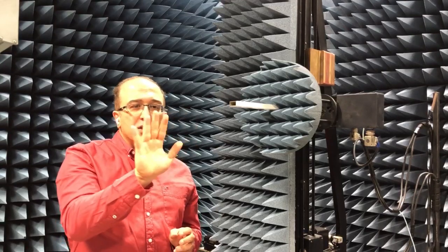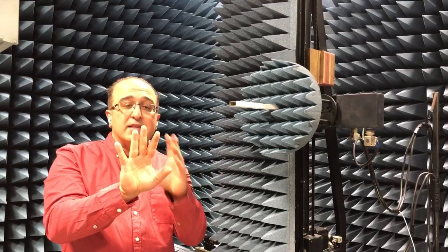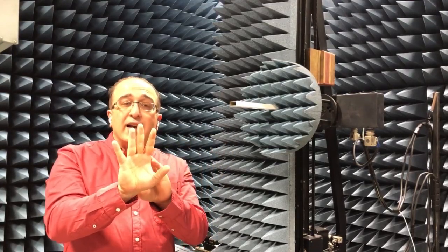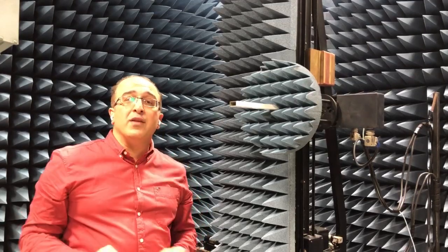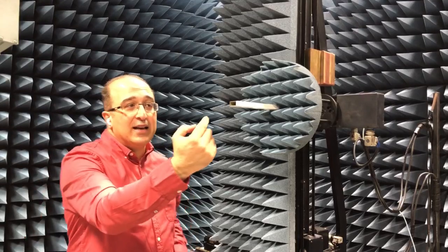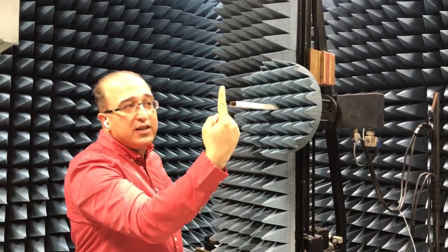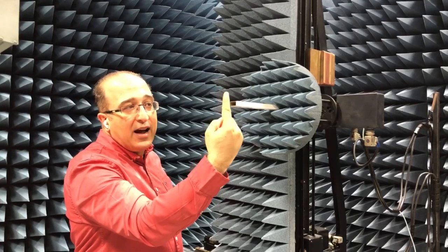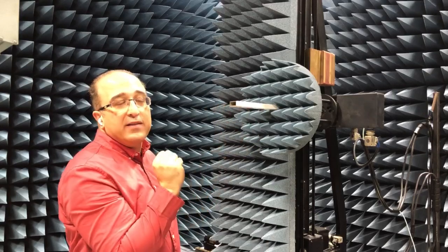So if you look at my fingers, for example, this is similar to the distribution here, that the electric field, let's assume we know the fundamental mode. In the fundamental mode there is a maximum at the center, and it gradually goes to zero, which is the electric field over the aperture. Remember that the electric field over the aperture is in this way, and it gradually gets smaller when you go to the two walls of the open-ended waveguide.